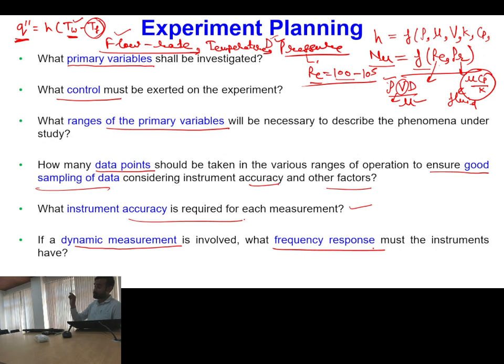And in the data acquisition system also you have to understand this point very carefully. Say the data card of a data acquisition system says its frequency is 100 hertz or 1000 hertz, and it can measure 10 channels simultaneously. When you are using only one measurement sensor, it can give you a maximum of 1000. But if you are using 10, then per sampling port you will be getting only 100. So you also have to decide how many high speed readings you require. Accordingly you have to choose your data acquisition system also.